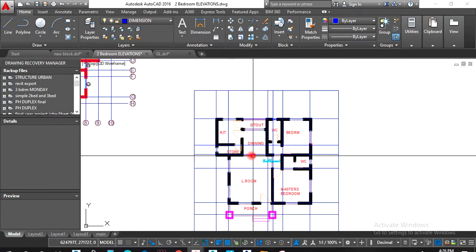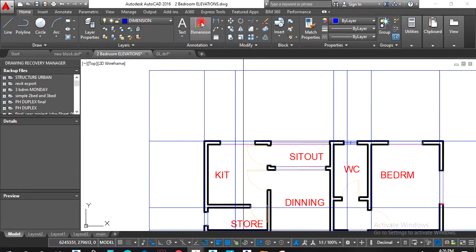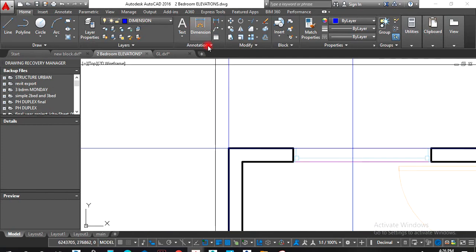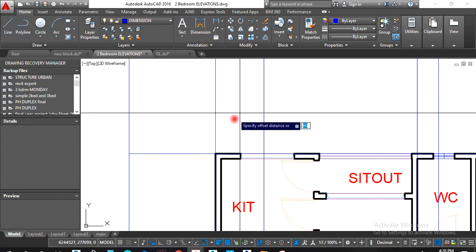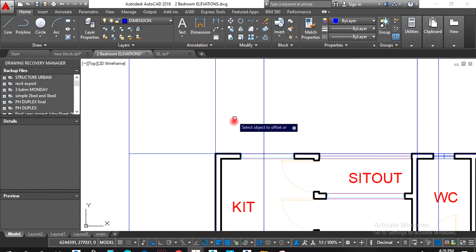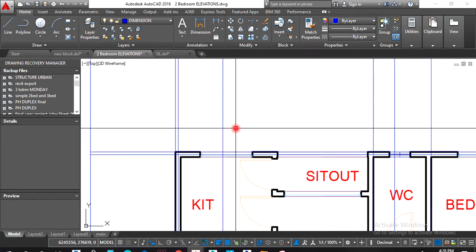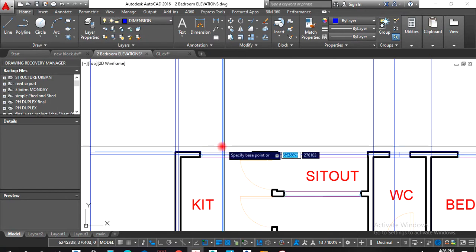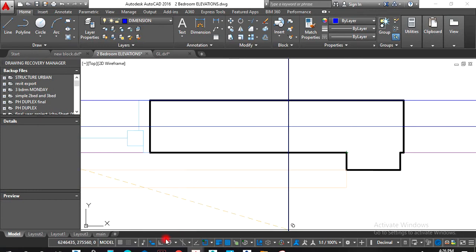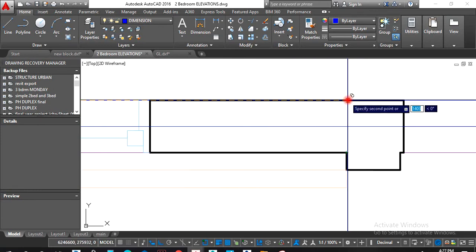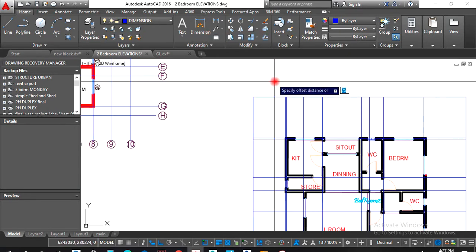So now after doing that, let's offset, let's check, let's measure under dimension. We'll measure our wall thickness, it is 150, so now offset it, so offset 75 each of these. I forgot to put a line here. I'll copy selection and drop, let me restrain this and drop it there. So I'll now offset 75.